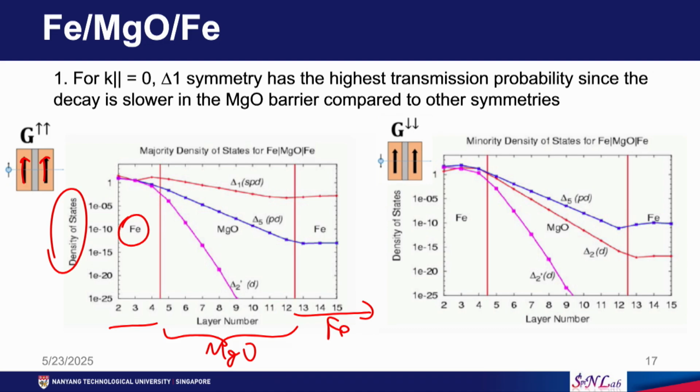Okay, so if the difference in the density of states is not much, then we can say that the bands match and the probability for an electron to tunnel from this side to the other side is higher. Okay. So say, for example, if this band does not match, here there is a large mismatch and so on. So this means tunneling probability is less, and here it may be almost impossible.